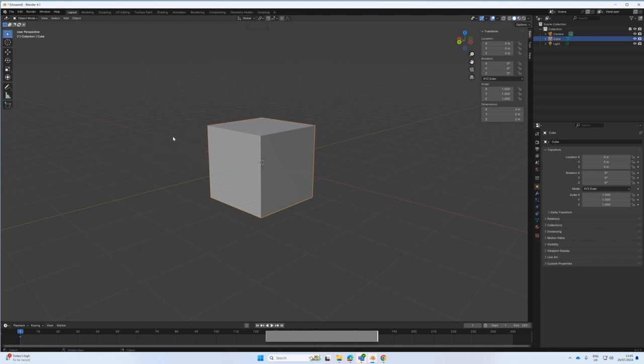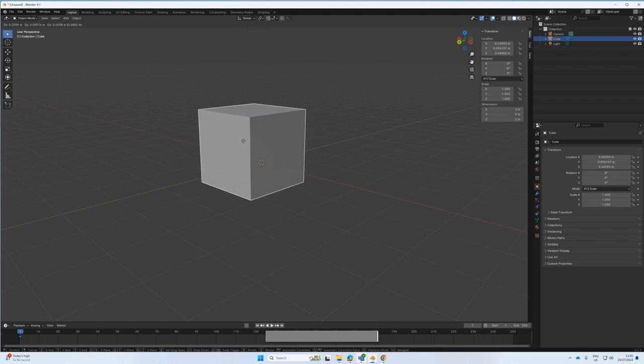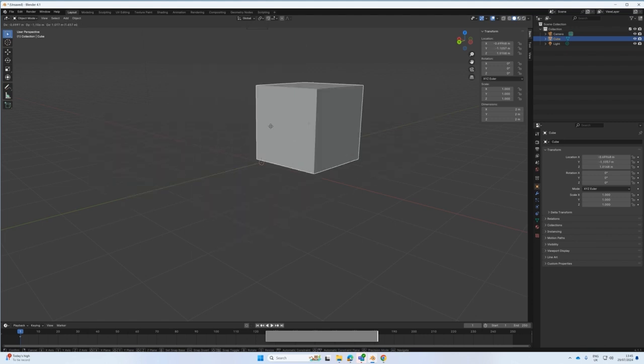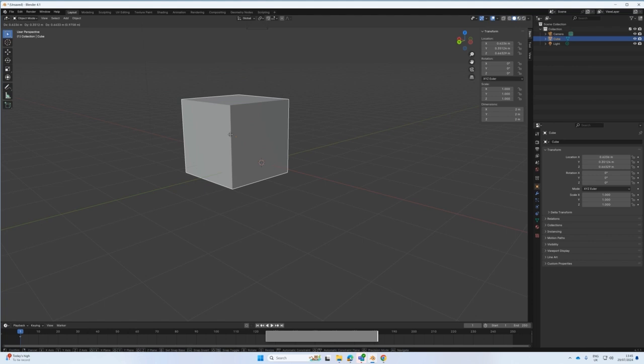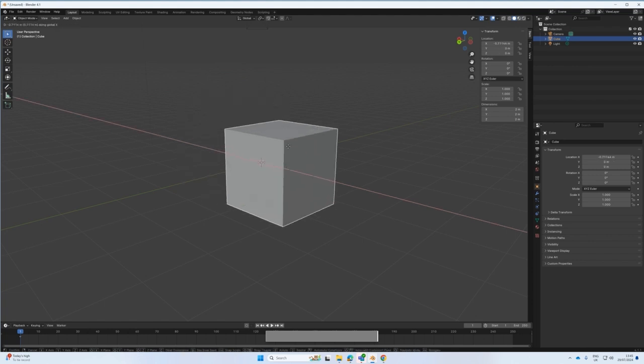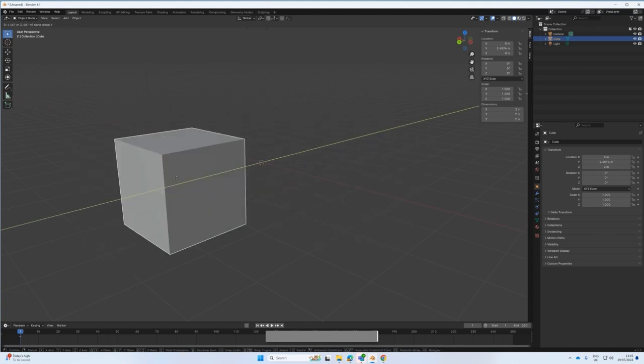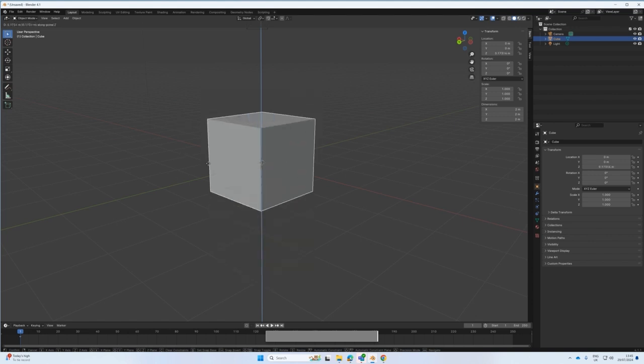So if you click here and that cube, they have some shortcuts for the transform, for moving. G is for move, okay? So if I press G, I'm moving, right? And I can't see those axes. But if I press X, it means I only move in X. If I press Y, I only move in Y, and Z likewise. So these shortcuts are very, very useful, right?